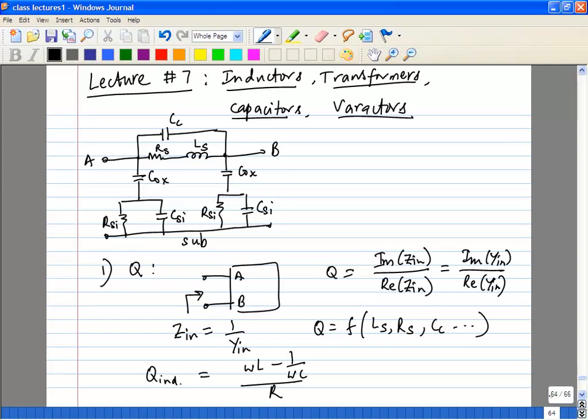So if we use a lower metal layer, the capacitance can increase because the metal layer is getting closer to the substrate. So the metal layer to the substrate capacitance is actually Cox. CSI is actually to model the substrate. Remember that it's a semiconductor, right?